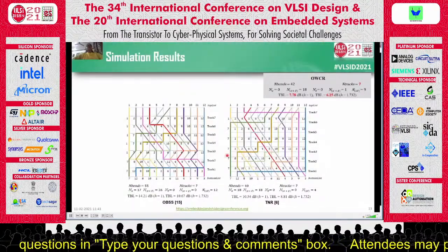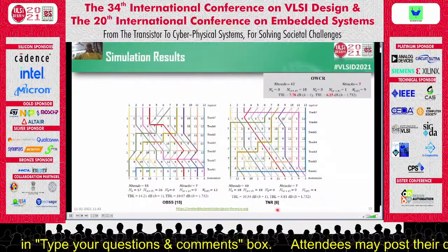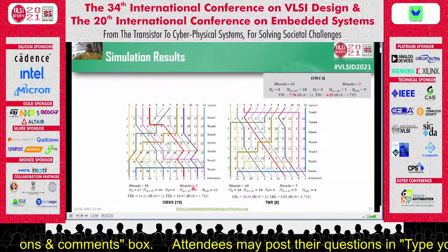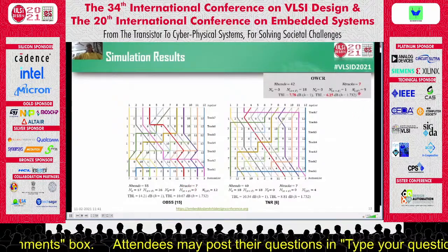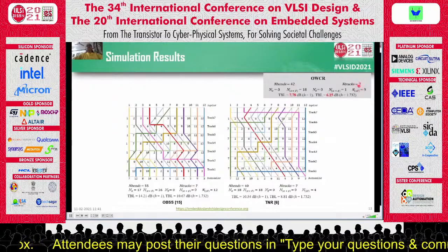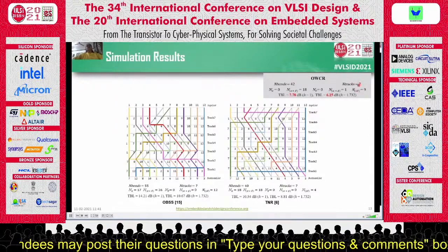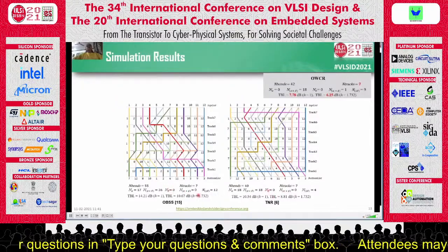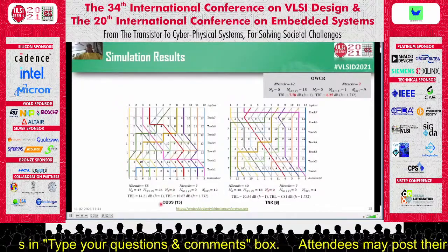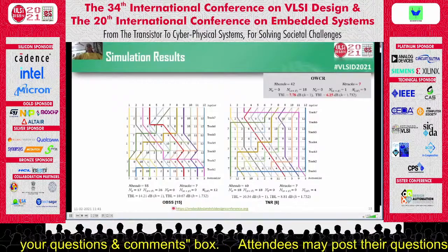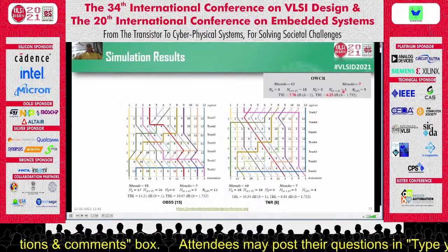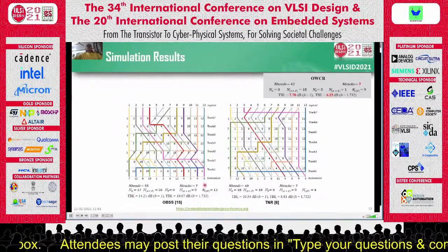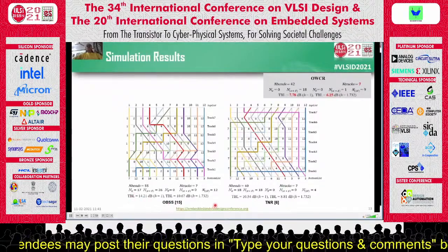Further, in the case of OBSS and TNR, we can see that they reduce the total number of tracks to 7, and OWCR is also using 7 tracks for this example. Further, there are no theta bends for both cases. However, the total bend loss for both of the cases is still higher than OWCR. This is because of the presence of alpha bends in OBSS and TNR.